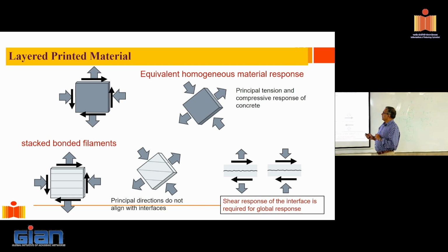And then we say, okay, now this is my principal state of stress. Concrete is going to crack across the tension, and I have to make sure that concrete can carry compression in the perpendicular direction. Wherever I expect to see a crack, if it's going to crack perpendicular to the tension, I'll put a tension reinforcement or introduce some kind of reinforcement to carry the tension. That's how I do my design, right?